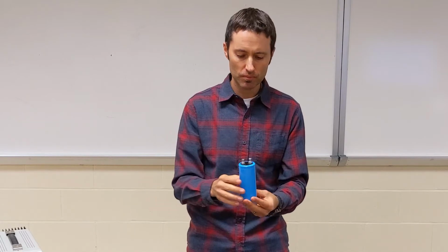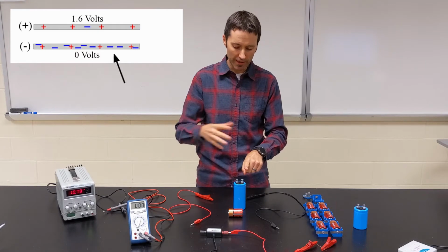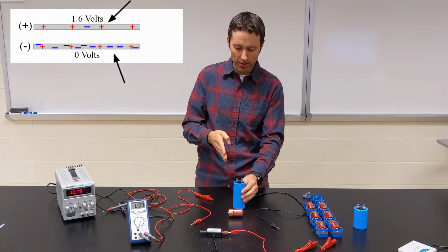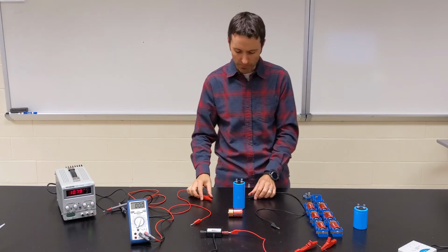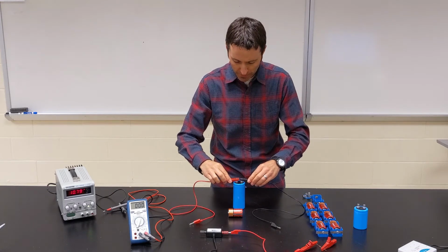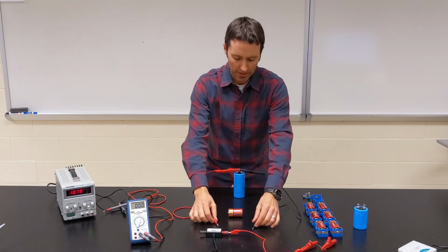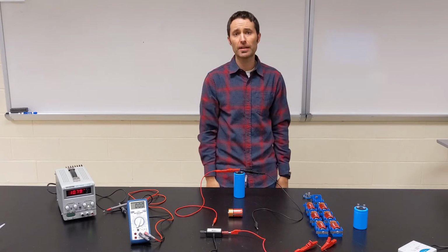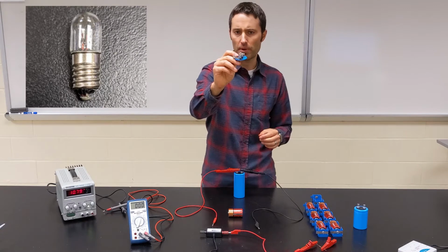So the question is, how can we get this thing back to neutral? Well, if there's an excess amount of negative charge here, they're pushing each other away, and they want to get to a place where there's missing electrons, but they can't do that through the air. We need to provide a conductive pathway from the negative side to the positive side. If we just touch these two things together, the excess electrons should go from the negative side back to the positive side, and everything should end up neutral. But I'm going to put just a little light bulb in between there.